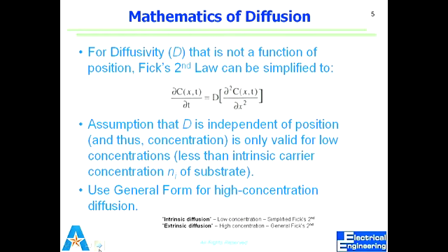Now, what is the intrinsic concentration of dopant? It is the concentration without the deliberate, extrinsic introduction of dopants. And what is the value of that? 10 raised to the power 10, right? That's what we call intrinsic doping or background doping, which is always there.